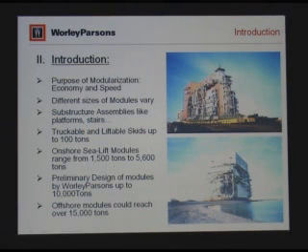Module sizes vary. We have modules like for substructure. This is also a module. What is a module? Basically anything could be a sub-assembly. We have everything from sub-assemblies to offshore modules. So platforms and stairs can be assembled into units. That's an assembly. You can have trackable, liftable skids up to 100 tons, which you can lift with a crane and then place on location. You have onshore sea lift modules, which we use when we transport them by sea lift. Those will be between 1,500 tons and the maximum that we did, which is 5,600.